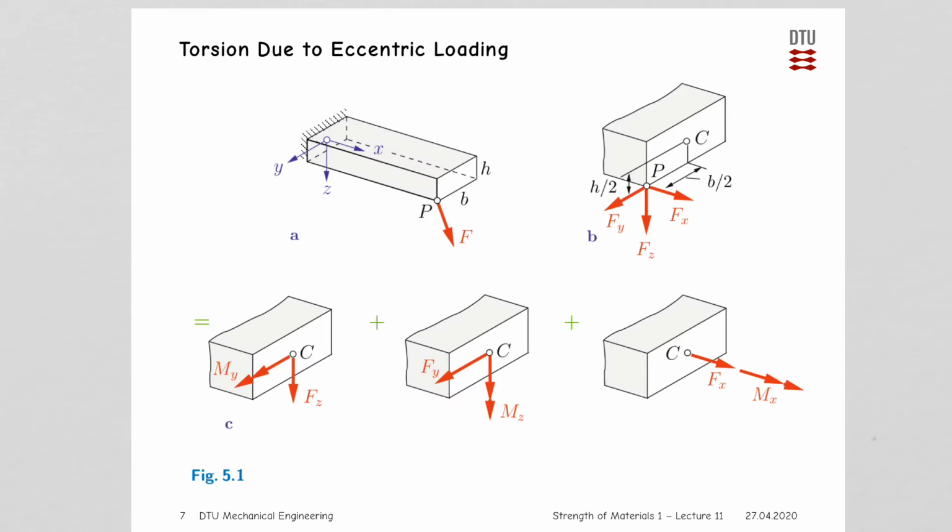Now, when we look at a very general three-dimensional problem, we see here up in the top left corner a beam structure subjected to a three-dimensional force F acting at the corner point here. Now let's see what kind of forces and moments that actually gives rise to. We haven't looked at such a general force before in the three-dimensional case. Well, maybe in the beginning in terms of statics, but not in terms of the stress resultants that it gives rise to.